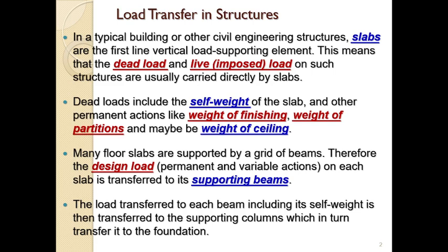What does that mean? When the load from the slab is transferred to the supporting beams, for each of the beams, the load transferred from the slab and the self-weight of the beam will be transferred to the columns that are supporting the beams, and the columns will in turn transfer the load to the foundation. And that is how load is transferred in structures from the slab down to the foundation.